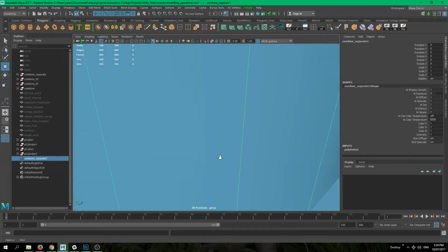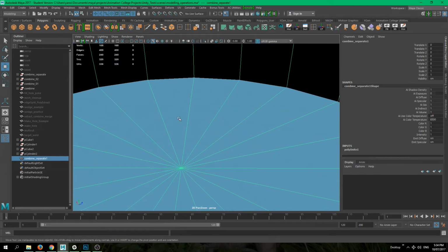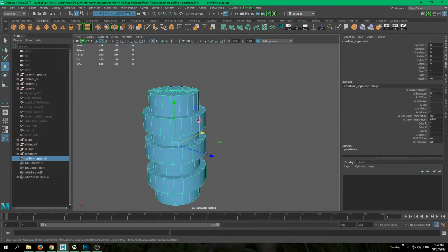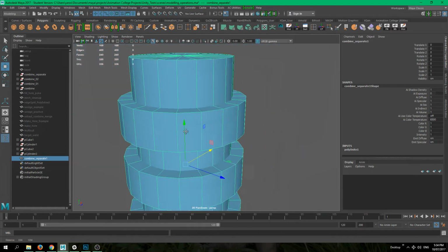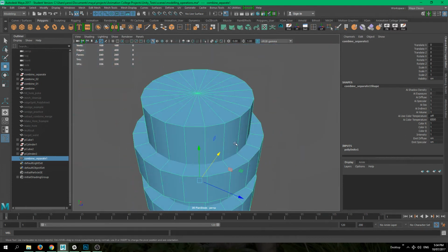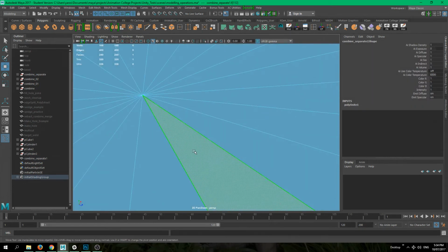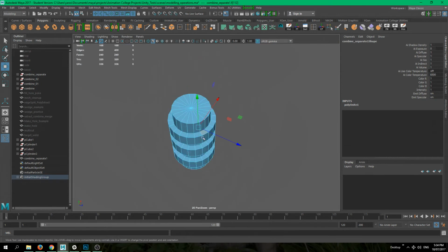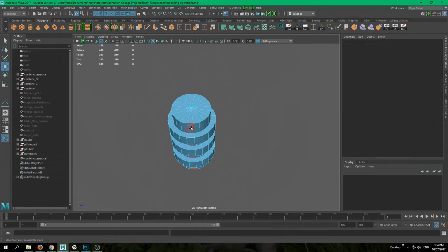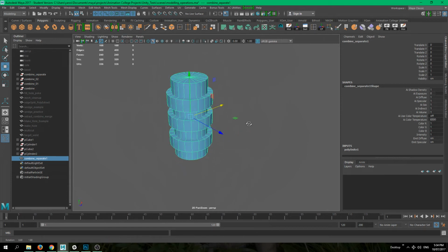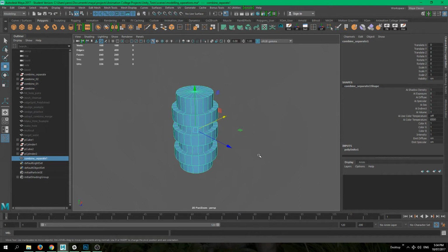But what we have here is we still have those polygonal faces inside of the object, so it hasn't actually done what Boolean was doing before. We can still manipulate those polygons separately. So if I click on this one and I go inside the object, you can still see it here. But if we go into our object mode, you will see that now Maya considers it to be one object. So from here, what you can do is to just rename it to whatever and make sure that you clean up your history and freeze transforms.